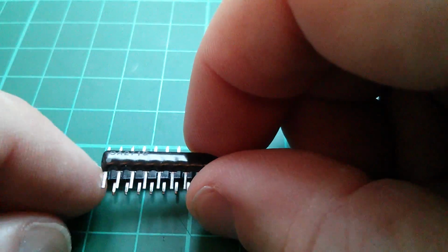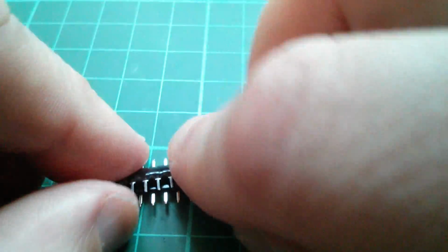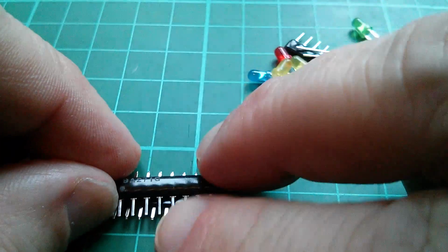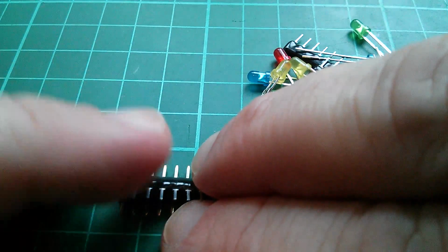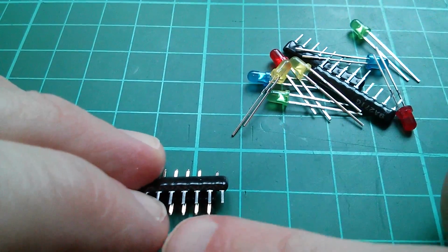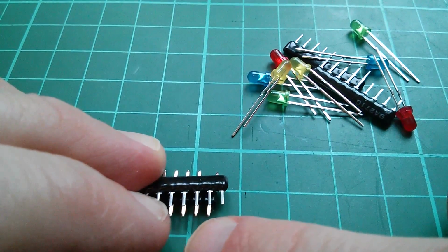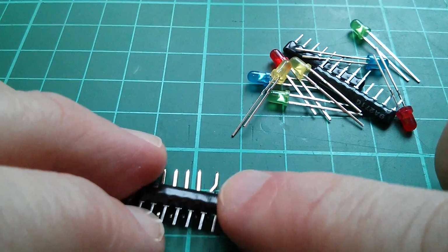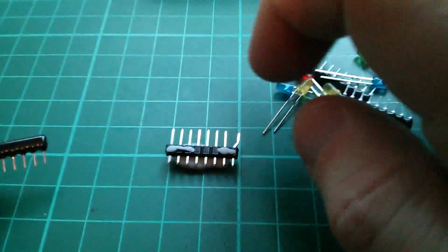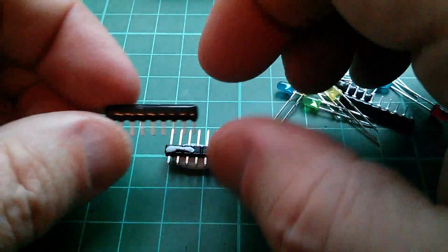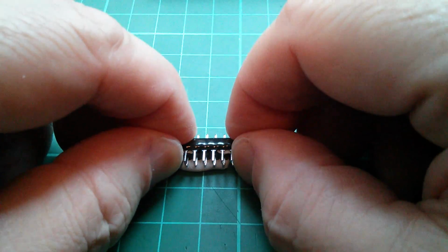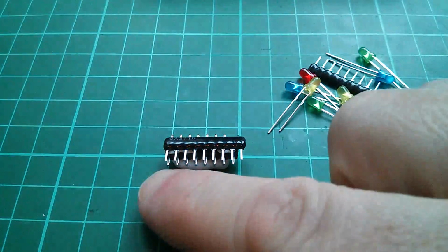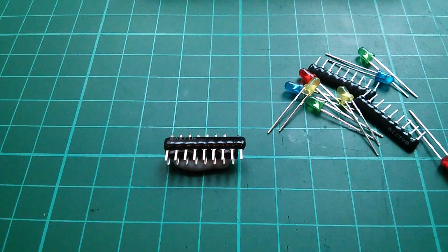Now I need to attach it to the header, a bit like stuck on top of the header, a bit like that I suppose. Pin 1, the common pin with the dot there, will line up with my last pin on the header so that I've got my ground connection, and then the LEDs will span resistor connections and connections on the header, including the very last one, which is bent out. Now I could use glue for this. I've gone with tiny amounts of Blu Tack there, so I just want to stick that on there so that all these pins line up, and then I can solder my LEDs onto pairs of pins down there.